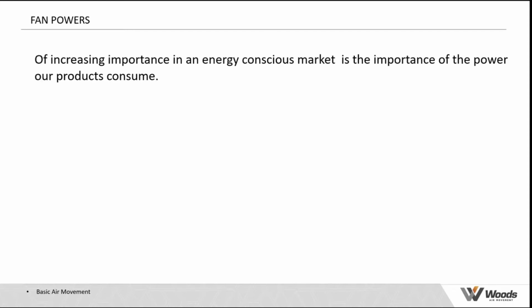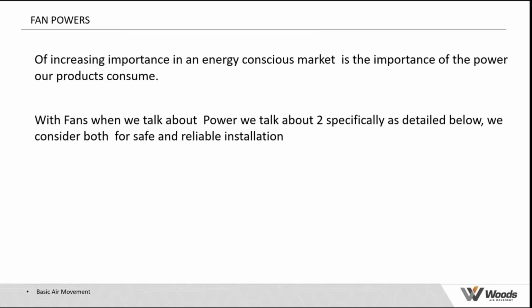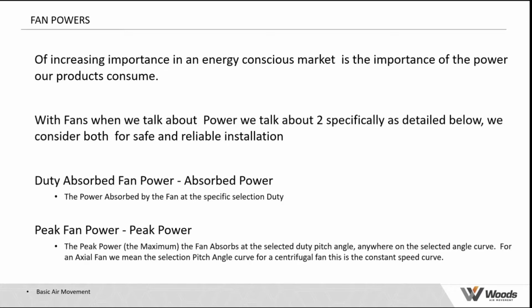So power in all of our lives, especially with the rising costs of power, has become very, very important. When we talk about fans and power, we talk about two specific powers. When we talk about safe and reliable installation, the first is a duty absorbed power. On our fan curve, we'll be looking at a little bit later, for any duty that will tell us what the absorbed power is. But also on that curve will tell us the maximum power that fan can absorb at that pitch angle.